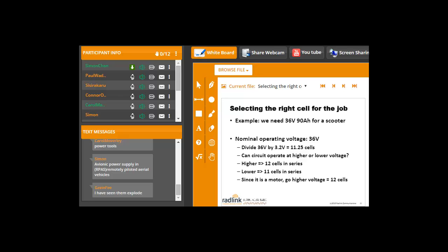All right, let's summarize. So you've got 12 cells in series. That is equal to 38.4 volts. Now, how did I get that? I go 12 times 3.2, and I get 38.4 volts. That's your nominal voltage. What's the minimum voltage? What can we run this thing down to?